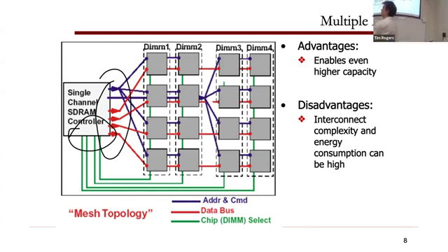The downside of this is that the more DIMMs you hang off of these pins, the slower it gets, right? Because you're hanging more stuff off of the same wires. So when you're manufacturing the motherboard, you don't want to have 100 DIMMs to plug in, because it gets slower as you have more metal hanging off of that. And if you actually plug them in, all of the capacitance from the circuitry hangs off of it, and you get all of these bad analog things that happen when you try to scale out to a crazy extent. But typical machines do have multiple DIMMs because DIMM capacity is limited and it's usually more cost effective to make smaller DIMMs. If you bought memory, this is obvious, right?